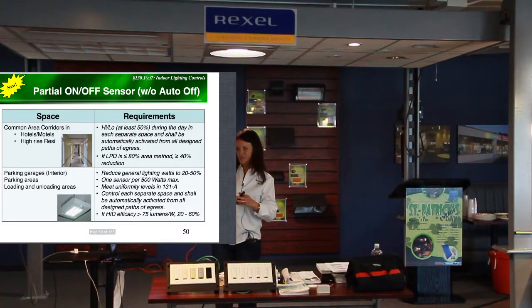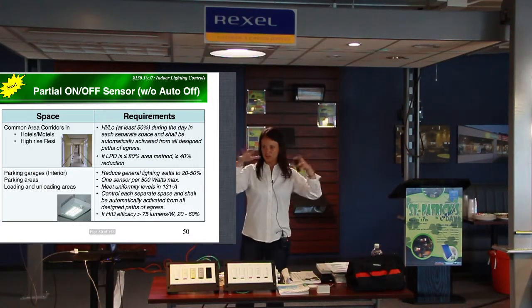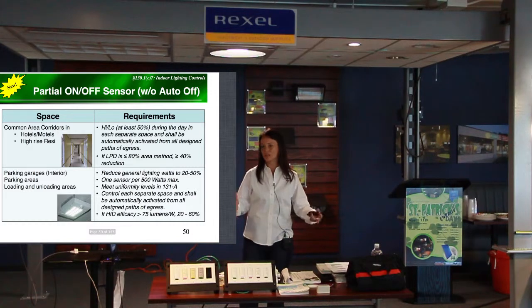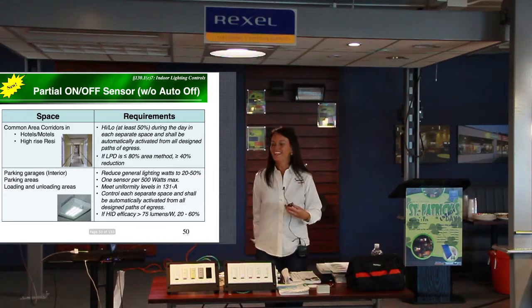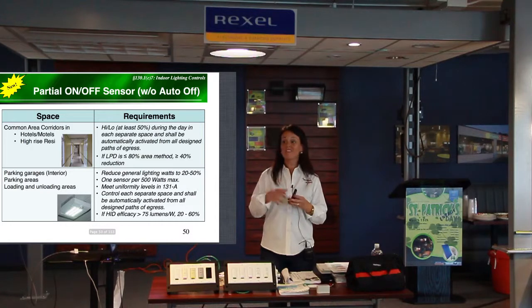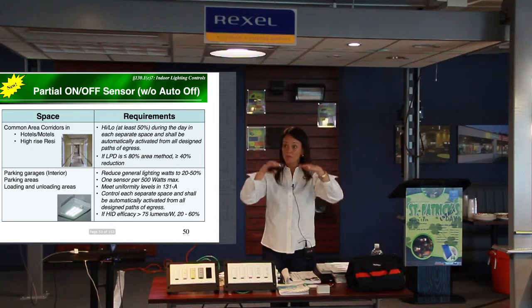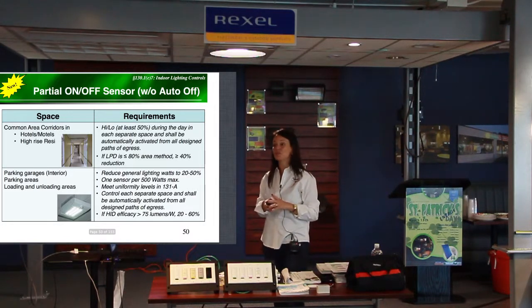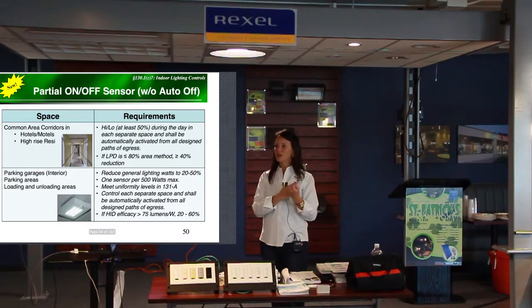If your checkerboard does not meet those uniformity levels, which is impossible, especially in a parking garage, you have a very long distance between fixtures. Yeah, so checkerboard is no longer acceptable in pretty much any bi-level application, because you have to meet those uniformity levels, and it's almost impossible to meet without doing either bi-level or dimming. So that fixture needs to have an A/B quality.